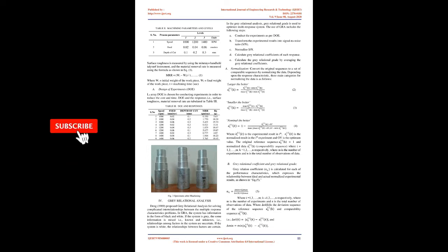B. Microstructure. To ensure the distribution of the reinforcement in the matrix, microstructure characterization was investigated experimentally by using an inverted metallurgical microscope. First the specimens were cut from the central portion of the composites, and then polished on the belt grinding machine for 2 minutes, and next polished on a disc polishing machine with different grades of emery papers for 2 minutes each, rotating the specimen 90 degrees every time, and then finally on a velvet disc polishing machine with alumina paste for 5 minutes, and then etched with Keller's reagent to remove the burrs and foreign particles.